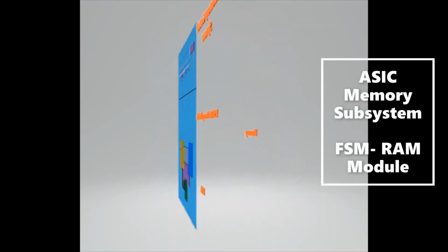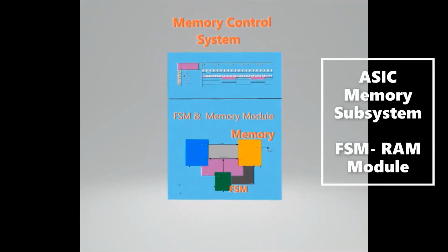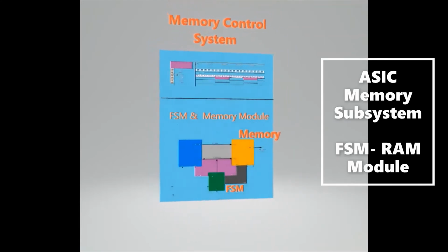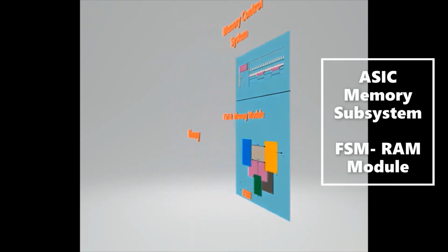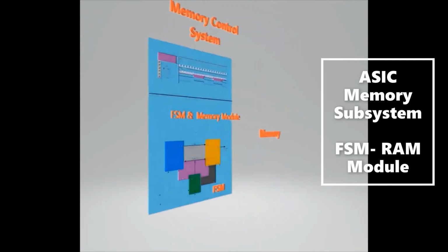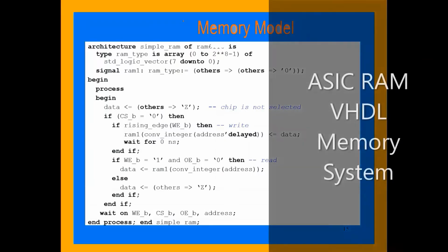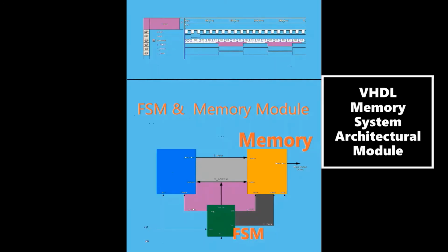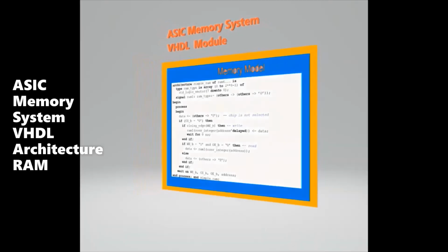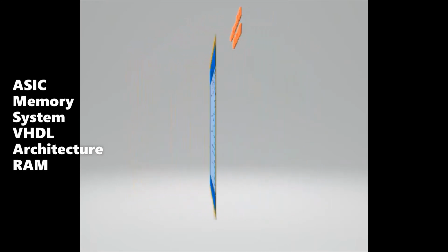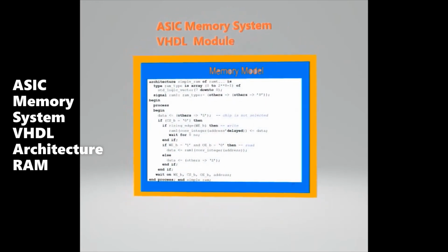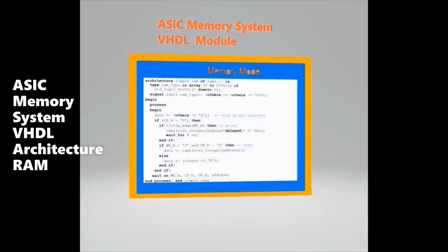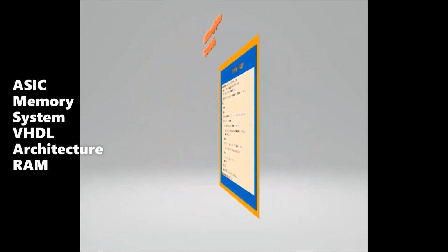When modeling fixed-size RAM memories, it's better to use an array variable rather than a signal for the RAM storage. On the right, the model looks to see if the address has already been used. If it is being used, the data is overwritten. If it is not being used, new storage is allocated for the address and data.